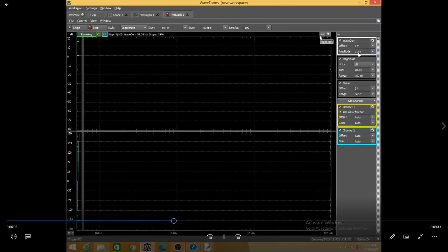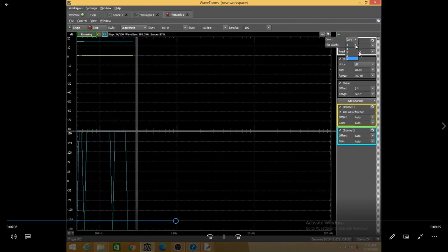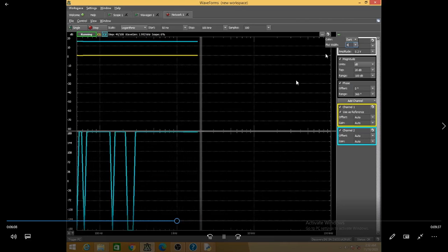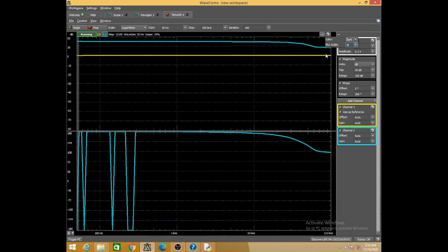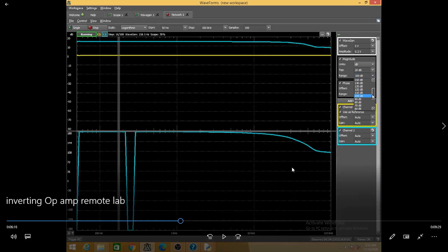Okay, also you can see that amplitude is 0.2. It should be a bit less. If it is more, gain times input amplitude should not go above your saturated voltage. Okay, sir. Now you can see, let me stop this, and can you see here, it is around this much, and you can see it is stopping here itself. So this much amount of space is being wasted. Am I correct? Yes, sir.